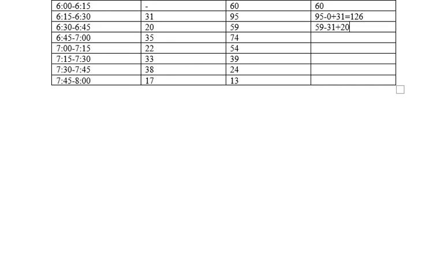Okay, so you subtract the previous queue, because these vehicles did not arrive in this time interval, they were already there. Okay, and then you add the present queue, because after subtracting the previous queue, whoever departed and whoever is in the queue, that is the number of vehicles which arrived during this time interval.